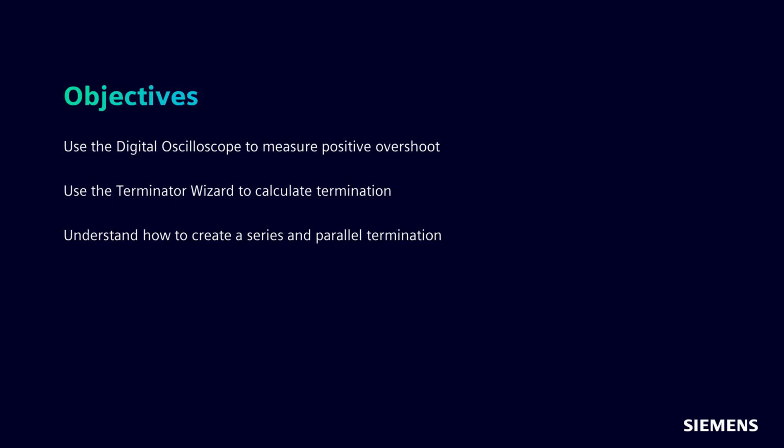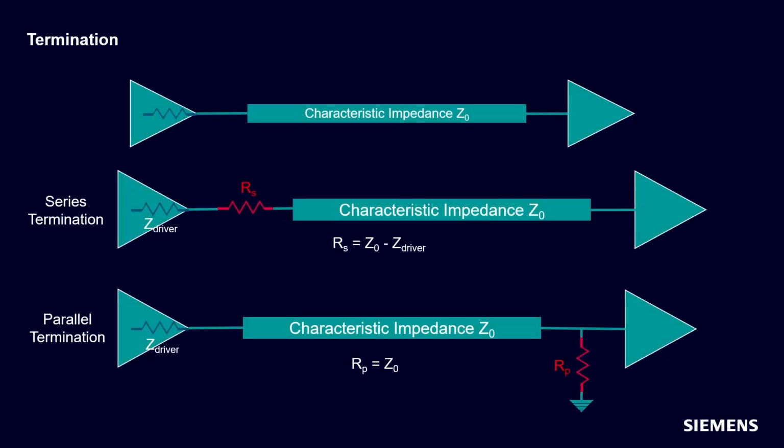As signals propagate along PCB traces, they behave as electromagnetic waves traveling through transmission lines. A fundamental challenge arises when these signals encounter an impedance mismatch. A portion of the signal energy can reflect back towards the source.